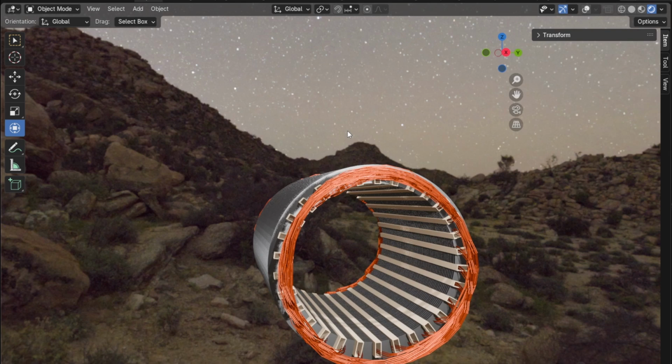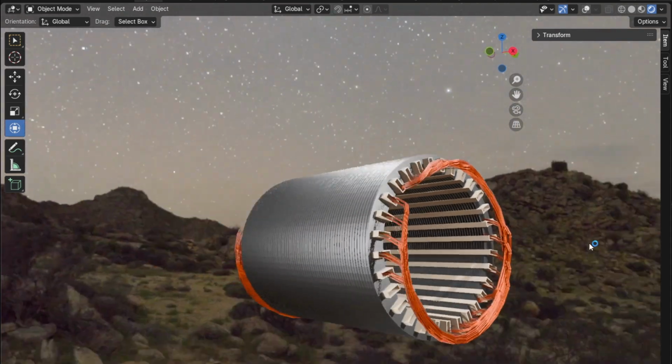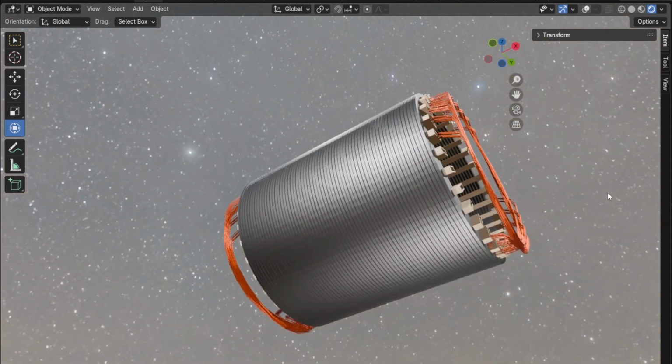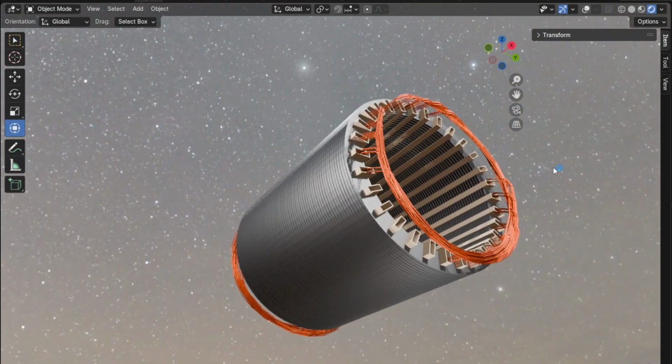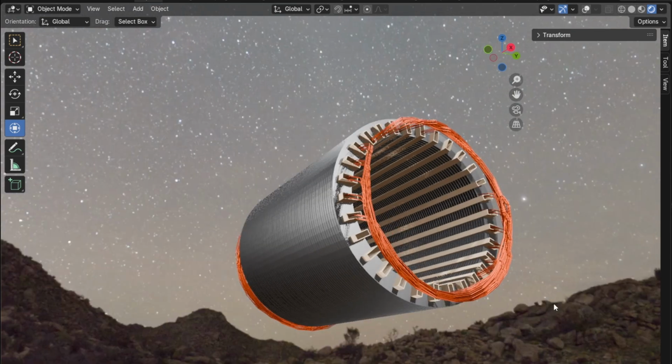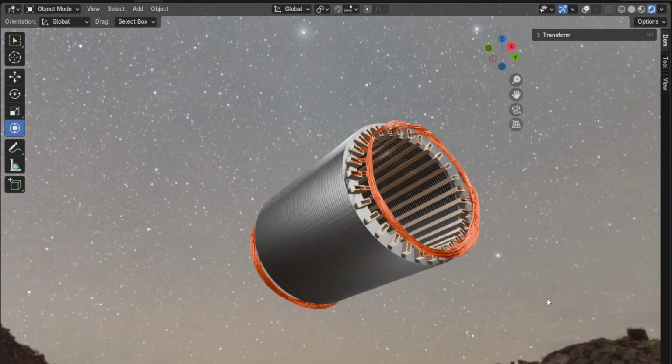So this is a three-phase motor, like I said. So we've got three identical coils around the perimeter of the stator, and they are offset radially around the stator by 120 degrees apiece. All right. And so remember, there are phases U, V, and W. If we take phase U out, then we're left with just these two. So that winding is gone now. And you can see we're taking up 5 slots here and then 5 slots down here. And what that tells you is that this motor is a two-pole design.